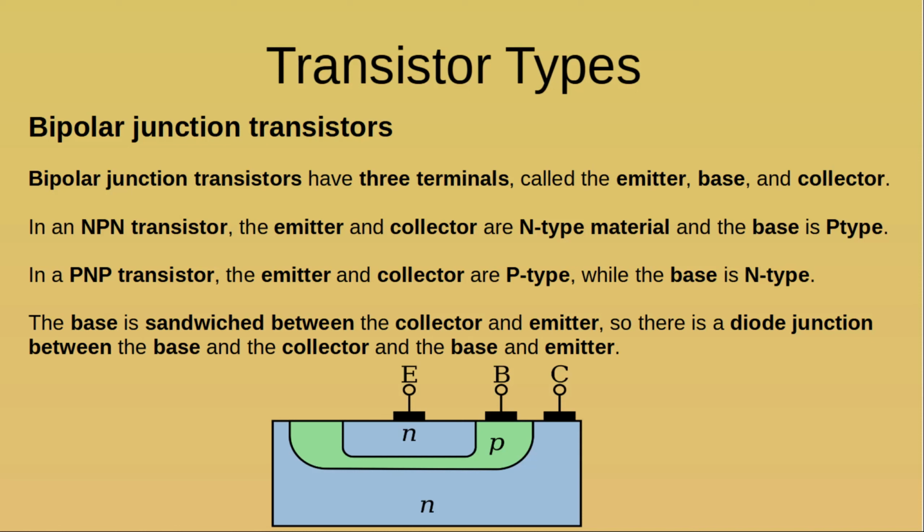But anyway, this is where we get the 0.6, 0.7 volts, which you need to bias the base to emitter to cause current to flow. And the more current, after you reach that voltage threshold, the more collector emitter current. So it's proportional, and it's a function of the gain, which is called HFE.